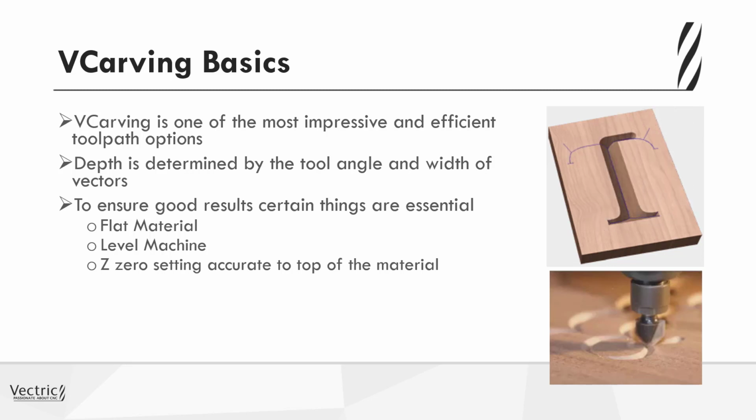We also need to have accurately sized tools. Even if our tool states that it's a 90-degree tool, it's best that we measure that, as even 1 degree out will alter the look of the part when coming to preview it, or even running it on the machine. Another aspect to tooling is to ensure that our tools have a sharp point and not a small flat, as this will also take away from the overall effect, and we also want to make sure that there are no dents in the tool too.